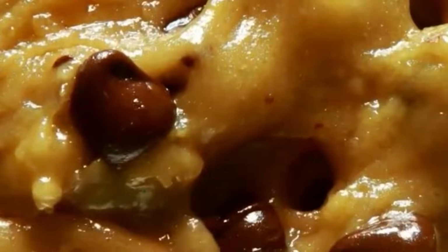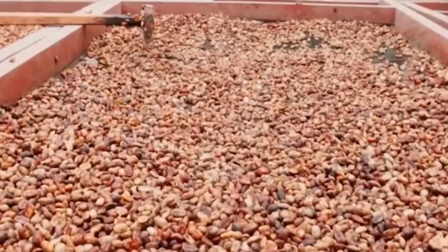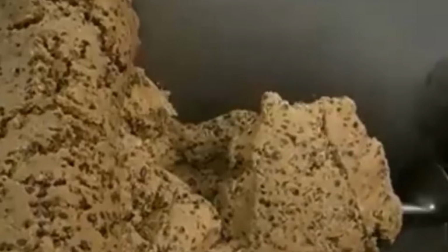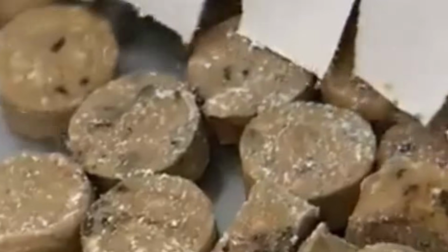Airflow in the cooling conveyor is managed by adjustable baffles and high-volume blowers. Zones are configured to prevent condensation or localized overheating, which could impact texture. Packaging film is spliced automatically using a festoon buffer system, allowing roll changes without stopping the wrapper. Splice detection sensors verify successful transfer and trigger rejection of the transition pack if required.